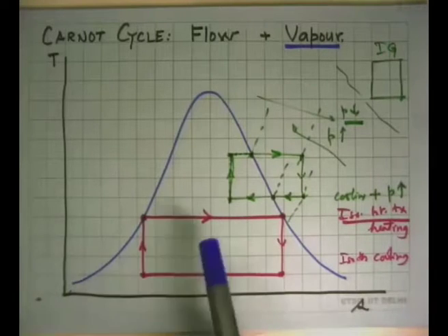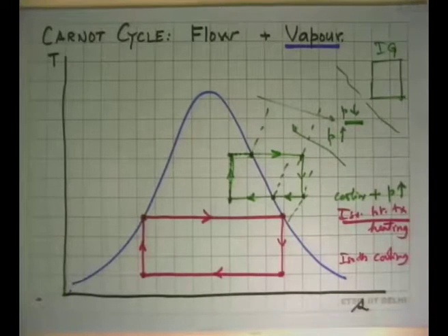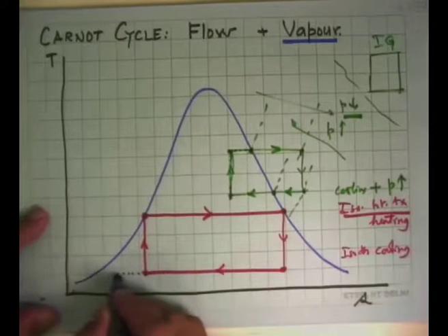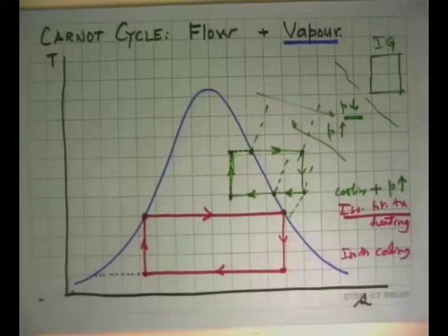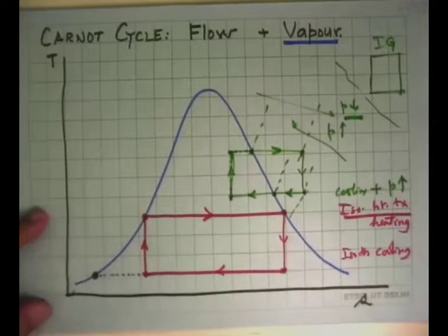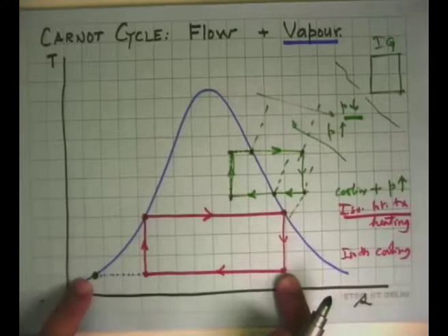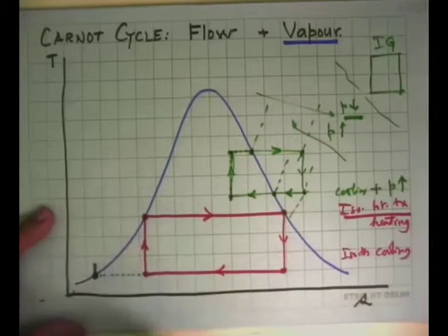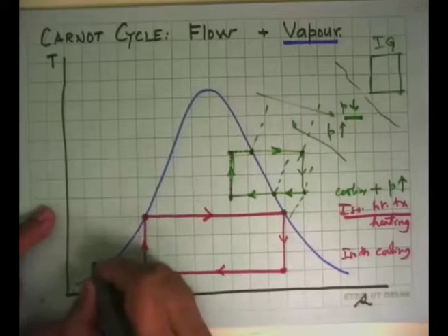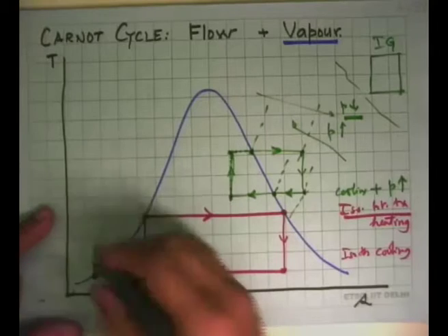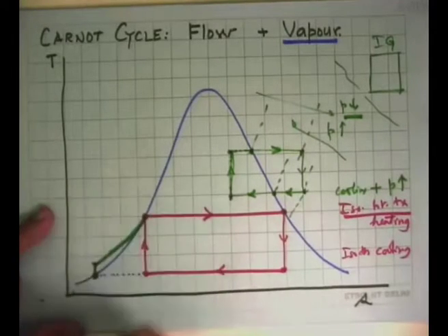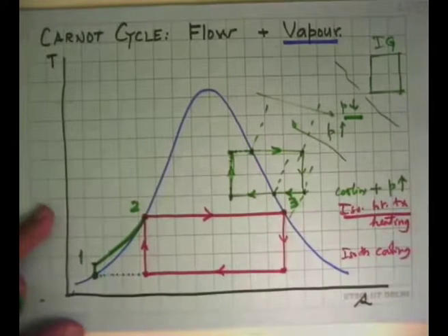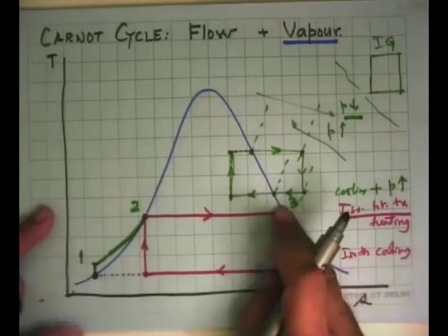What we have is a modification of this Carnot cycle. And we say that, look, I want to make it practical. So instead of condensing it here, we will take it all the way there and condense it over here. So this to this is condensation. Now we have liquid, we can make a pump and compress it. And at this state, we can then begin the heat input process and it will go from here to there. So now 1, 2, 3 is our heat transfer process. It is happening at constant pressure, so possible.